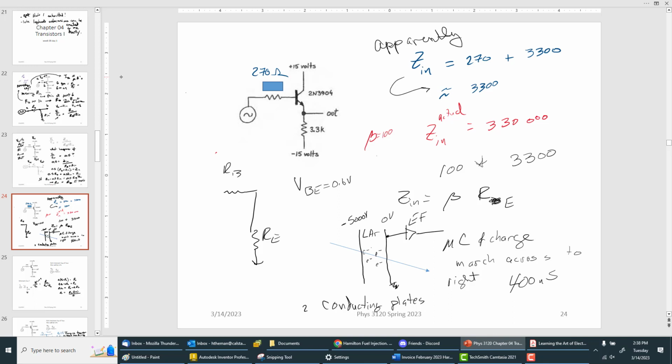So this is similar to the analog voltmeter weighing down a circuit, right? So you want any amplifier to have a very high input impedance. That's your goal. And that's what a transistor does. Before transistors, you used vacuum tubes, and that's a good question. I don't think that they could achieve a 1 mega ohm input impedance, because of course, they weren't used for this kind of signal.